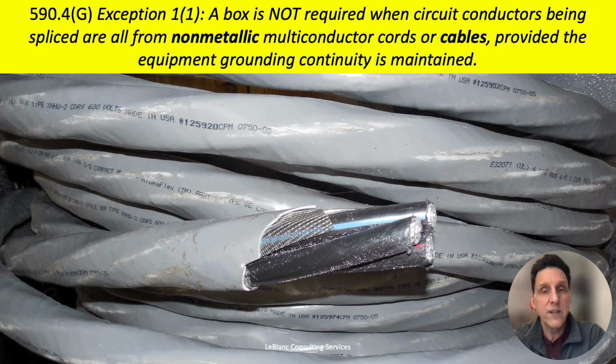Now we could do the same thing with SER cables or SE cables. These are also non-metallic cables. So if you wanted to splice feeders, you could do that without a box, as long as you maintain continuity of the equipment grounding conductor. Okay, so it doesn't matter if it's a branch circuit or a feeder. So it would apply to cables like NM cable, SE cable, SER cable, UF cables. These are all non-metallic cables.